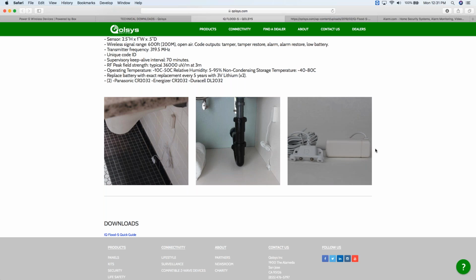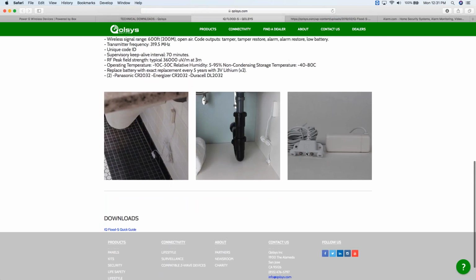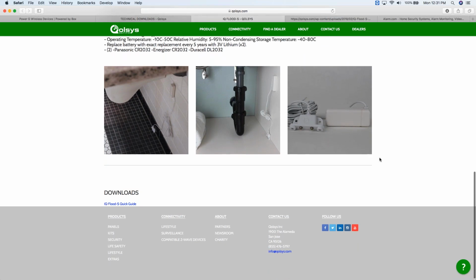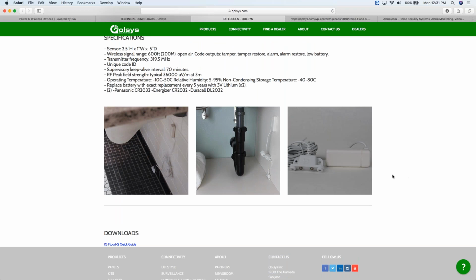So your technicians that are testing this can do it a number of different ways, right? I mean, obviously they could stick this probe in a bowl of water. Most guys will just use their little mini screwdriver and short those two contacts. If you just put your screwdriver in between those two contacts, that can cause that sensor to trip. I've seen guys stick this on their tongue and trip it that way, right? Not really recommended to lick your sensor until it goes off, but I've seen it done. Point is, we want to short these two contacts to get that sensor to trip.